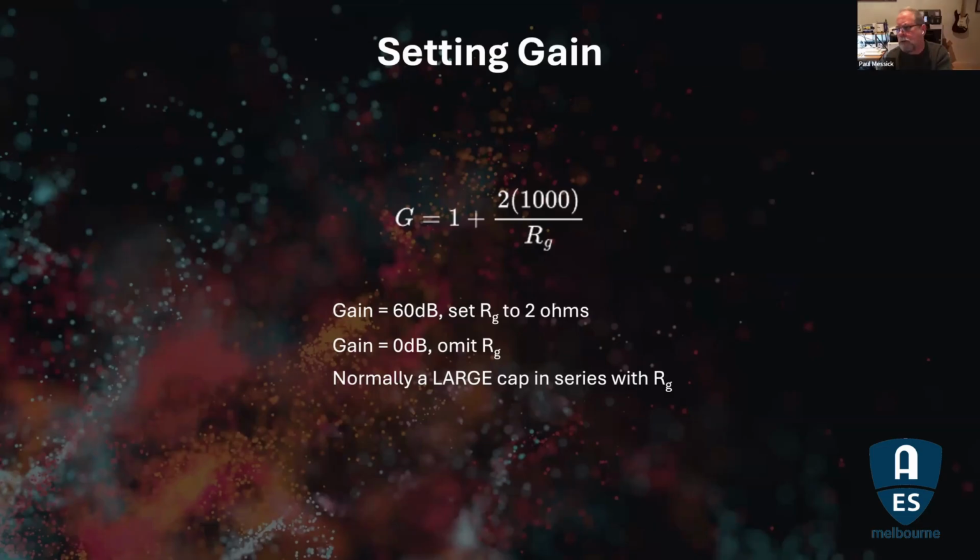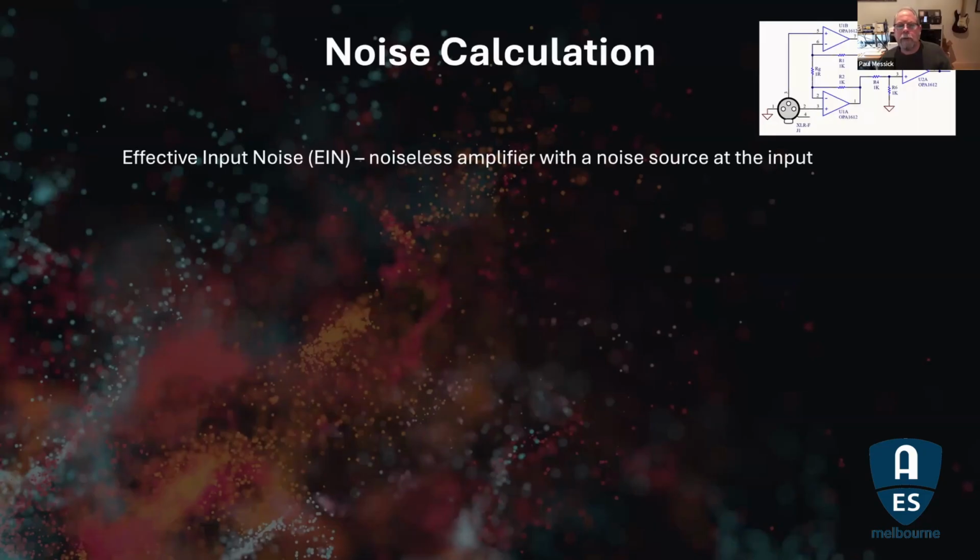And then in most mic pre's that have a knob, all of them with a knob, there'll be a large cap in series with that resistor, that pot, because otherwise you get some voltage across the pot and you get scraping noises. They're very noisy with any DC on them. But as you can see, we've omitted that here because we're just going to plug a resistor directly into it. There's our little mic pre up in the corner there, just for reference.